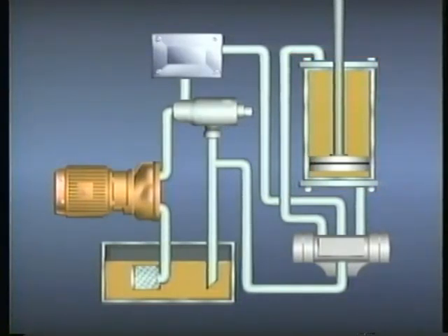During operation, hydraulic fluid first passes through this strainer on the pump inlet line. The strainer traps small particles and prevents them from entering the pump and causing damage. The fluid continues through the line to the pump. The pump's basic function is to convert mechanical power into hydraulic power by applying force to the fluid and moving it through the system.